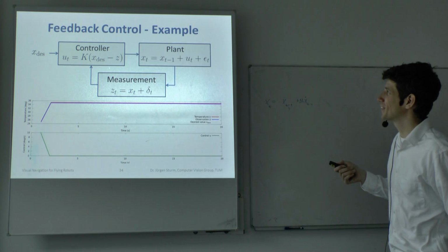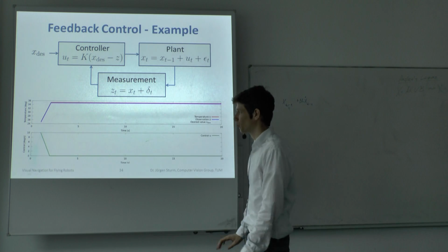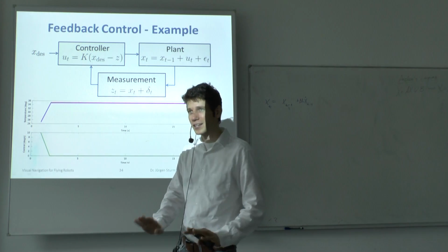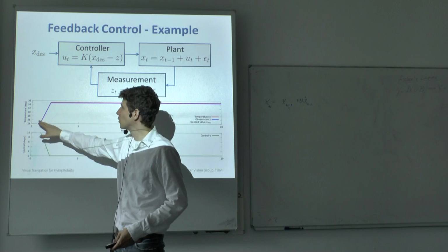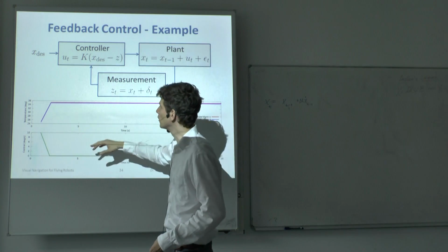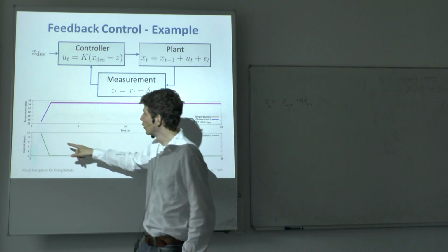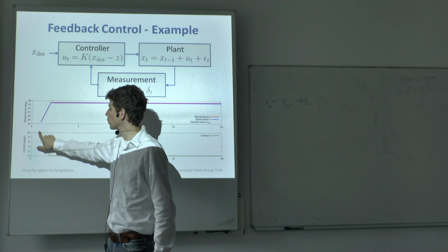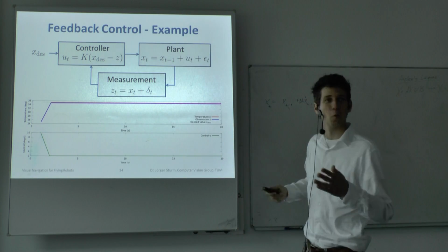So imagine we set the gain to 1, and we have no noise and no delays. Then, yes, when you have a system like this, you apply exactly one time step, and it will immediately jump to the desired temperature, right? Because you only have to give once a control of, in this case, the difference is 10, so you give a control of 10, and in the next time step already you have reached your target value, so everything is fine.